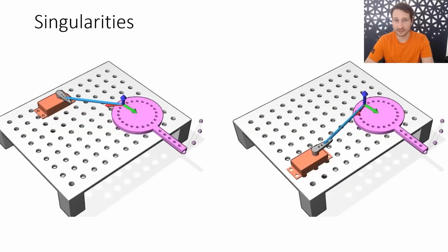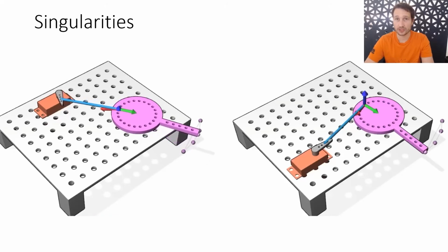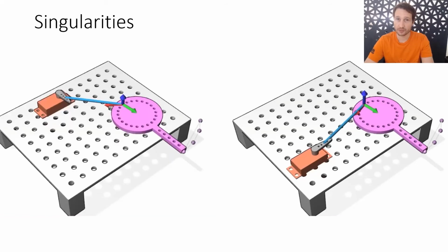When maximizing this dot product, which is basically the inverse of the moment arm, we maximize the moment arm. Through this maximization, we also tell all the connections to stay as far away as possible from singularities. Here, on the left, we can see, if we don't maximize for the moment arm, how the blue arrow, resembling the moment arm, changes its direction. So it goes over 0. And on the right, where the moment arm is maximized, the blue arrow stays close to constant over the whole trajectory.